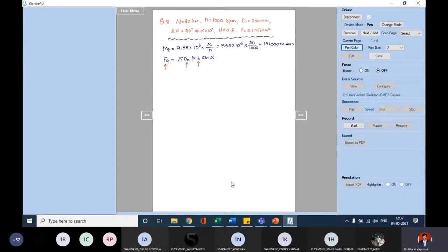Okay, we'll go with something like D1. We know the concept. D1 is equal to dm minus b sin alpha. Let me substitute the relation between dm and b. See what we used to do: I need a relation between dm and b, so we will get the relation from here. D1 here is given as 300. So dm minus b sin 10 degrees.